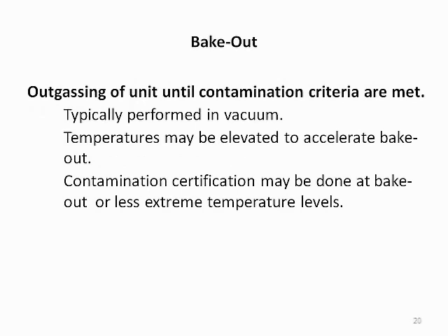The final type of test to be discussed here is bake-out. The objective is to outgas volatile chemicals present in the materials from which spacecraft components are constructed in order to minimize contamination of sensitive spacecraft components such as optics and radiator surfaces. Bake-out is typically, but not always, performed in a vacuum at temperatures above the normal operating range of the component.